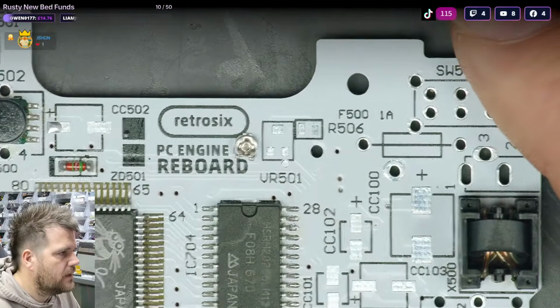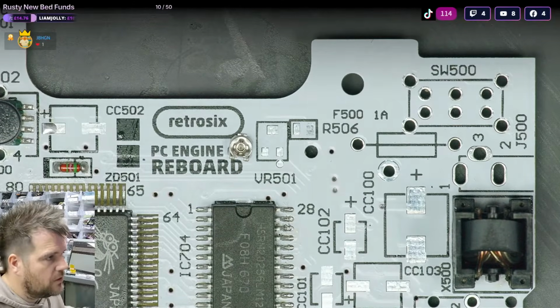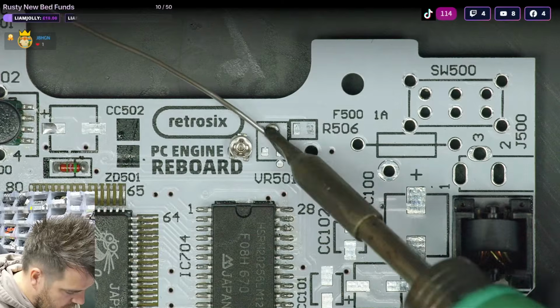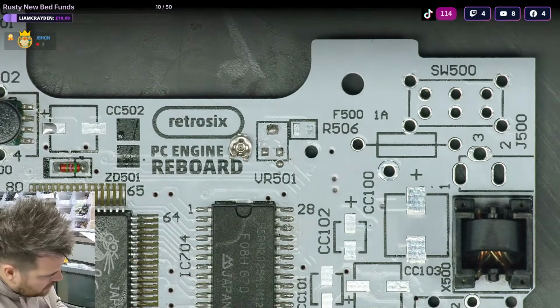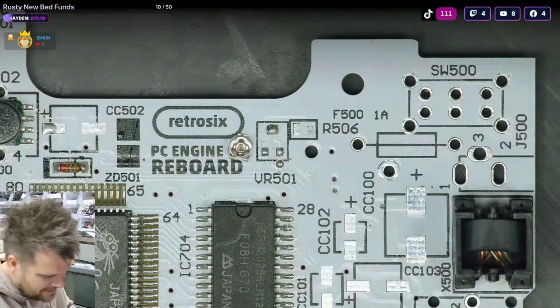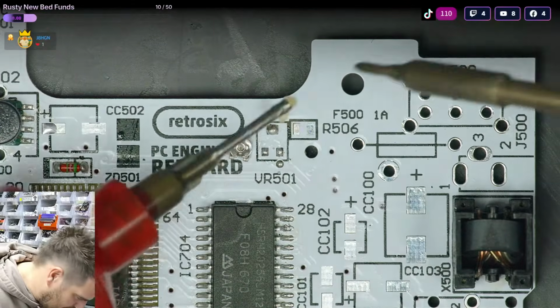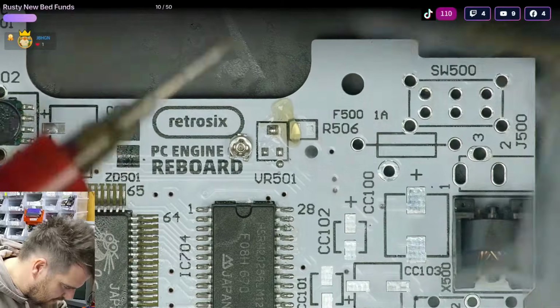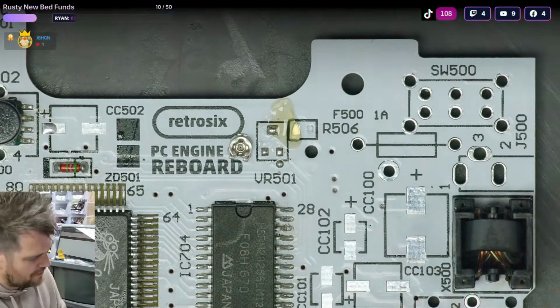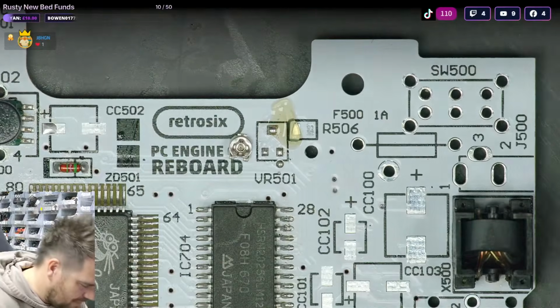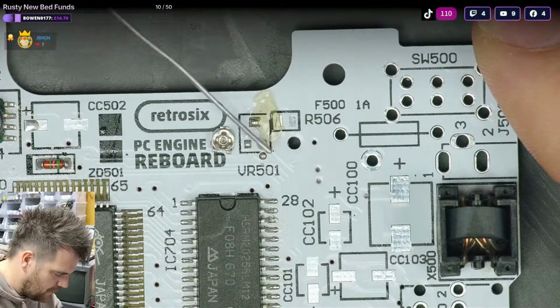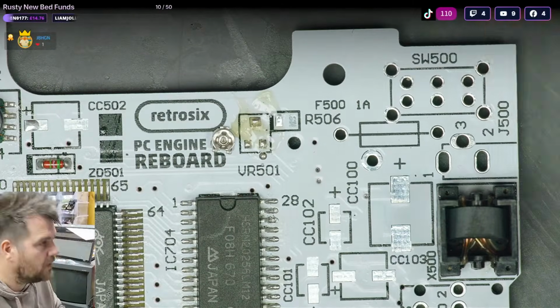These can be hot aired on, so long as you don't take too long, or you can melt them. But if you know what you're doing, hot, hot, hot. Just as I say, if you know what you're doing, I flick solder right on my finger. Right in between the grooves of your finger as well. It always goes on the hottest spot. Went right between there. Boiling solder. So now, if we've got that on, we can hot air this on.